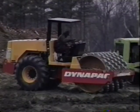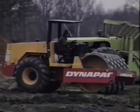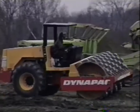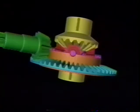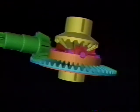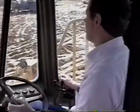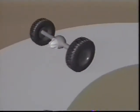When the vehicle is traveling in a straight line and both drive wheels have equal traction, both wheels travel at the same speed. Remember, the pinion cross gears are forced to revolve with the cross, but they're free to rotate on their own axis when required. When the vehicle goes into a turn, the inside wheel does not turn as fast as it did in a straight line, but the outside wheel turns faster because it has a greater distance to travel.